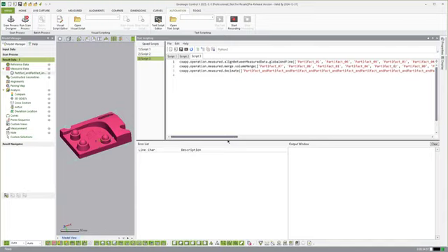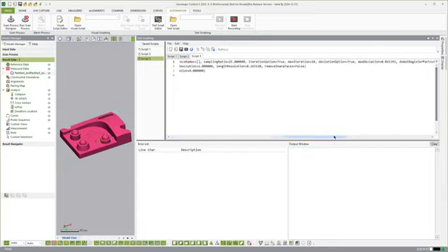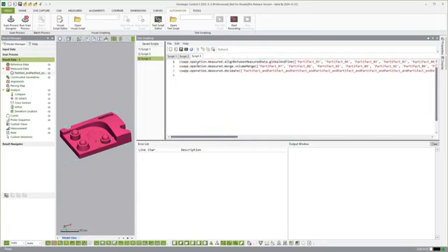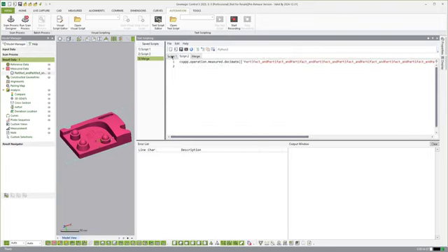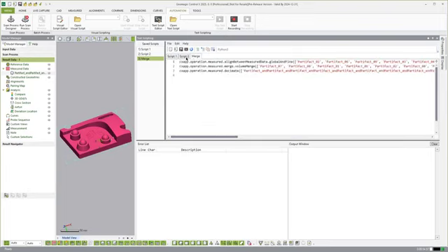And then you'll see here it does the volume merge with its settings available right here, and then it does the decimate. So then if I needed to rename this, you just come over here, and I could just call this merge, and then hit OK there. So now we have, again, these different tabs open, and you could even save this script and run the next steps and save another script and copy and paste them in and use the scripts in stages.